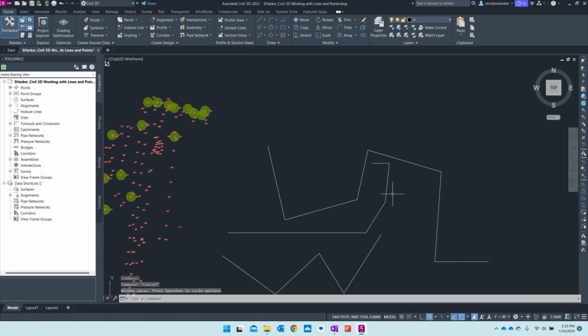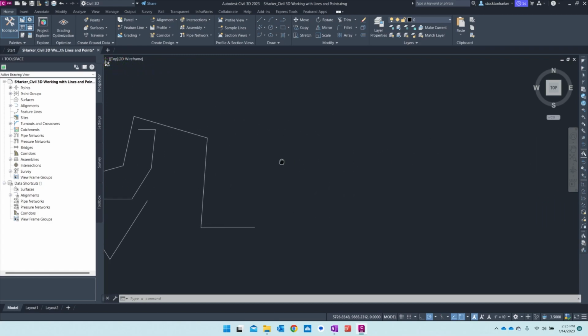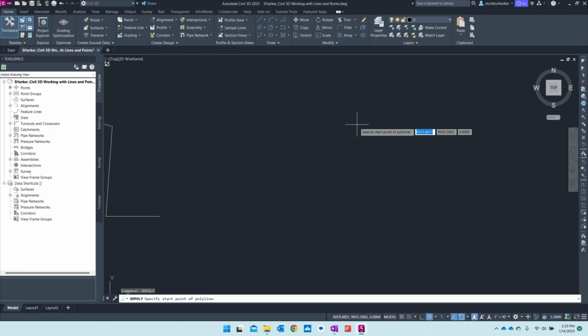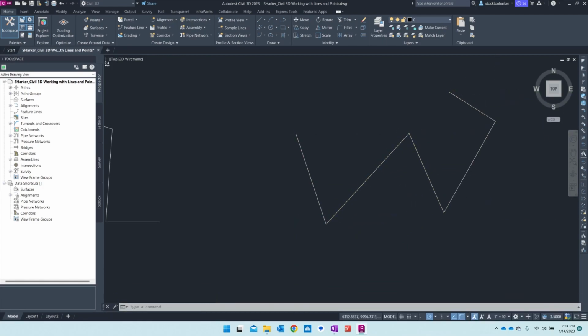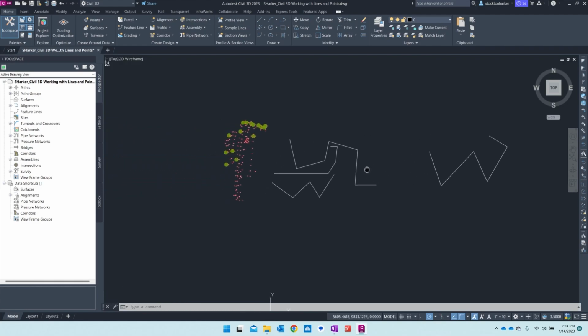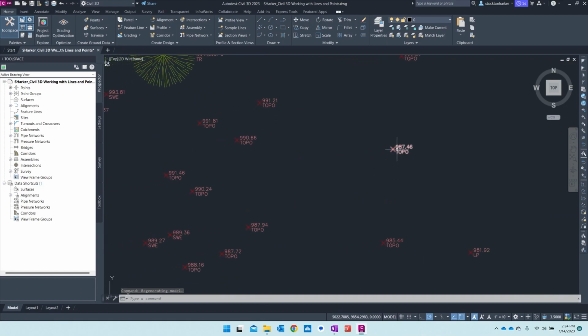The next command that will be important is like a polyline, but it is the 3D poly option. So to do that one, it's 3D poly. And when you start drawing, you'll notice it appears to be a lot like the polyline command. The only difference here is that the 3D poly will actually draw on a three-dimensional plane, whereas the polyline will only draw 2 dimensions.